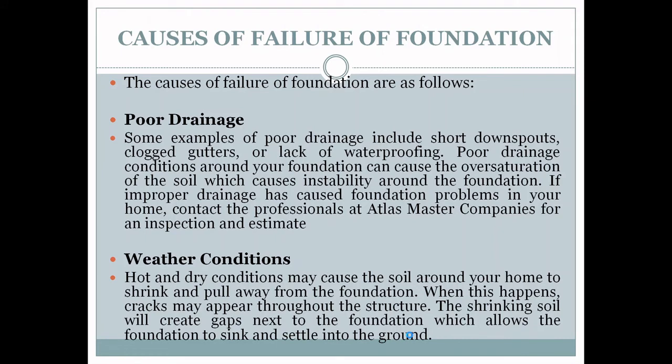Causes of failure of foundation. There are many causes of failure of foundation. The first reason is poor drainage facility. Poor drainage conditions around your foundation can cause oversaturation of the soil, which causes instability around the foundation. So how can we avoid the settlement of the soil? By providing proper drainage facility around the foundation area.